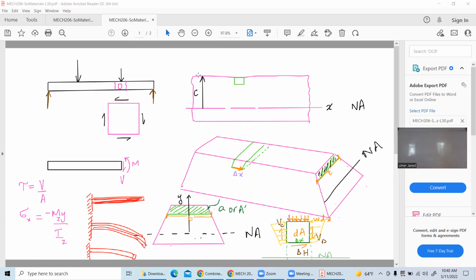The whole point is that when you have a beam on which you are putting load, there is definitely a shear like this, right? But the point is, even between the layers in the longitudinal direction, you have this shearing, right? So essentially what we want to do is we really want to have an expression for the longitudinal shear.